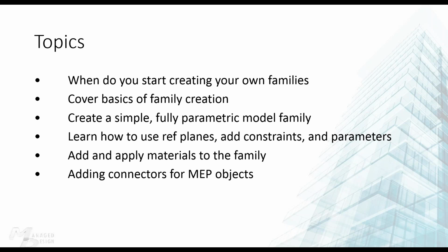So today's topics, obviously we're going through families, but when do we start thinking about creating families? We're going to be talking about the basics of family creation. I'm going to be creating a very simple parametric model. I'm going to show you how to go in and create your reference planes, add constraints, add some parameters. I'm also going to go in and apply some materials to your families. And then I'm also going to show a little bit about connectors for MEP objects.